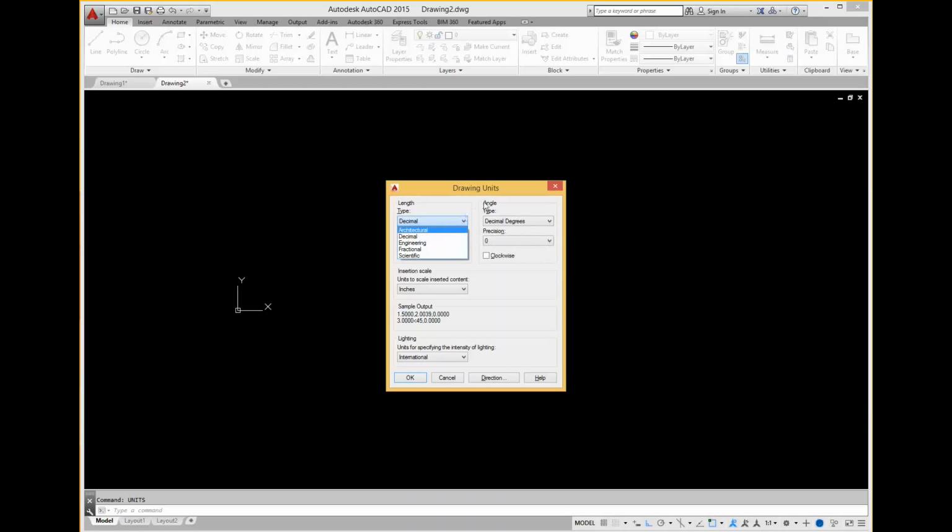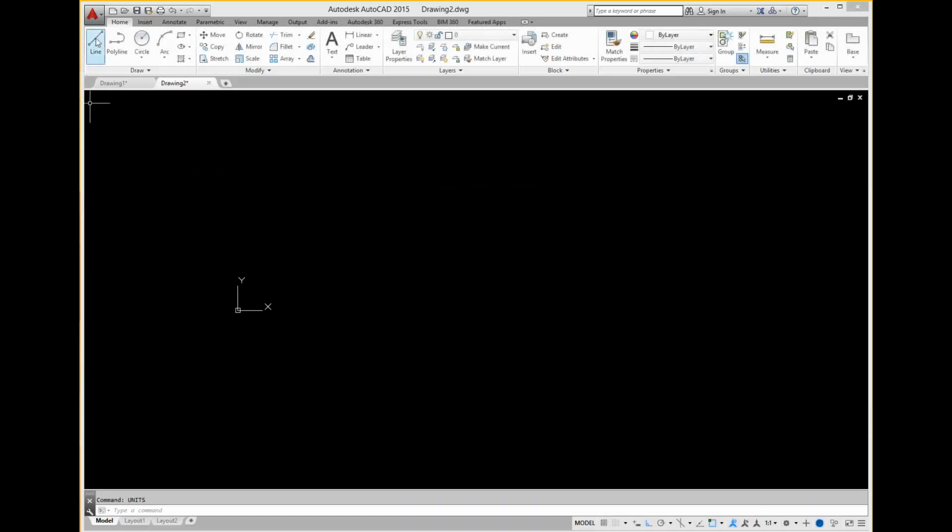So under this tab here, click architectural, and then OK. And now click on the line again, pull down, type 27 apostrophe for the foot, and enter. Now type Z, enter, A, enter. That's zoom. This didn't work, so I'm going to escape. Z, enter, A, enter.